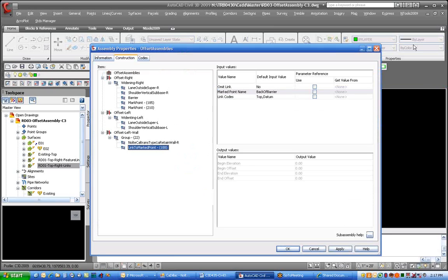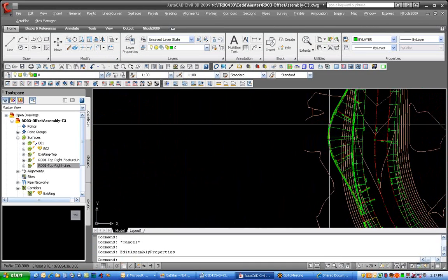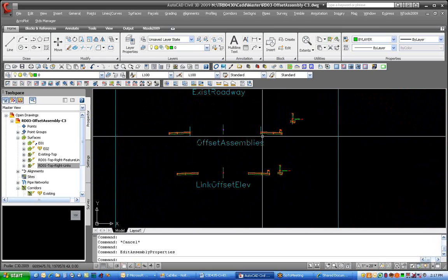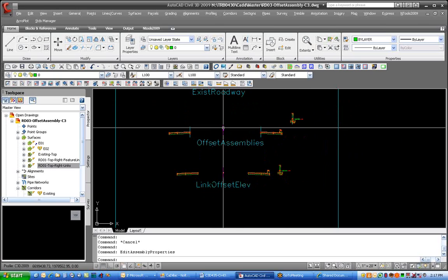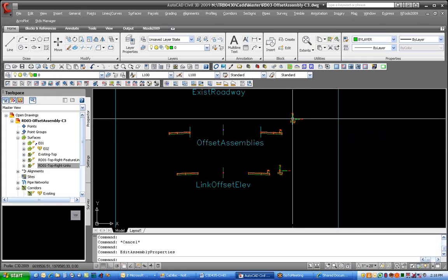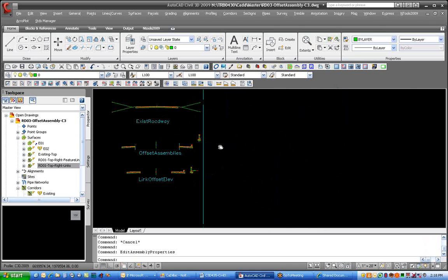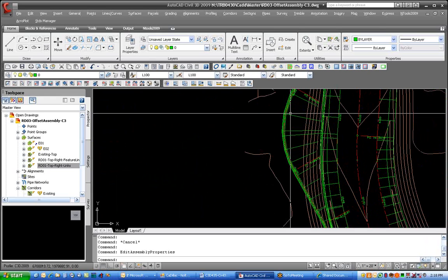Okay, the way I fixed the radial issues I had with these lines being radial to the wall, not to the baseline, is I changed the order I built it. I built this one first, then this one, then this one. What we need to do is build your assembly, but then add the non-radial one first, then do this one, put the mark point here, and then put the link here, and I'll change that in just a bit. You'll see the big change in that these lines will now be radial coming up this way, and it'll give me a much better model.